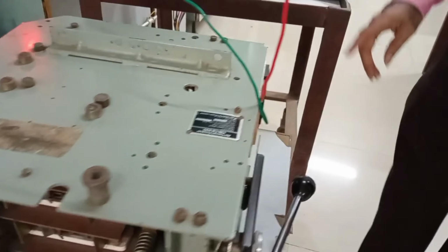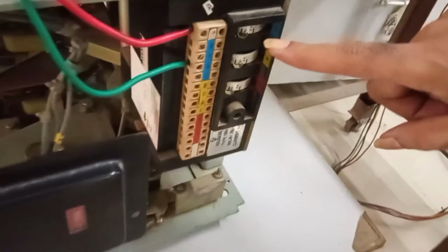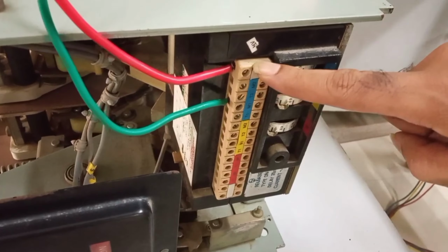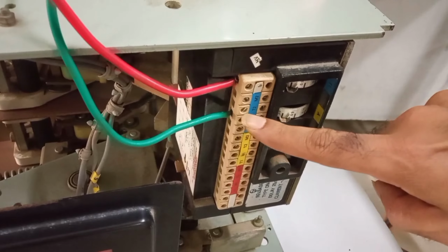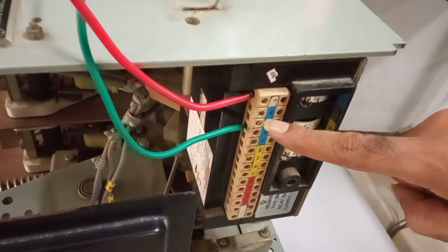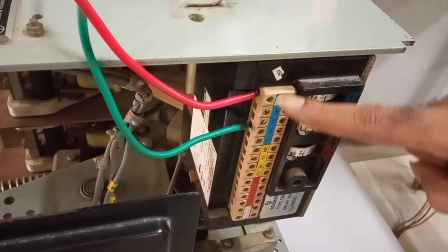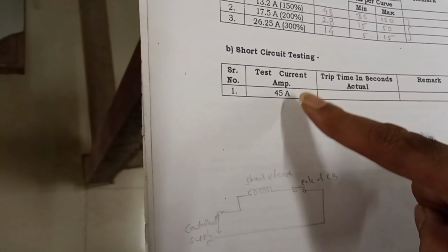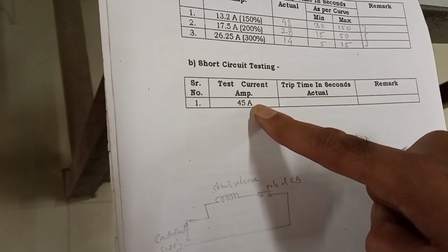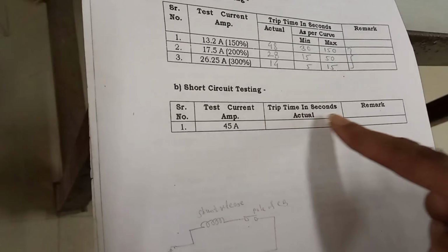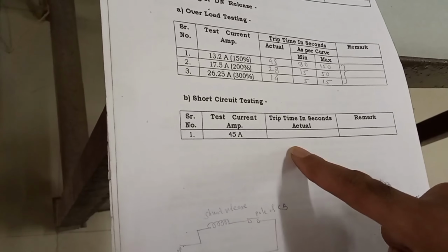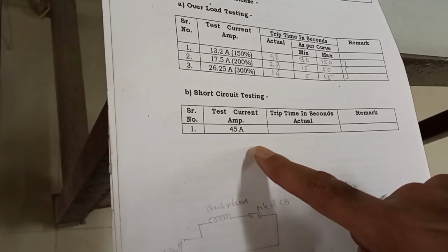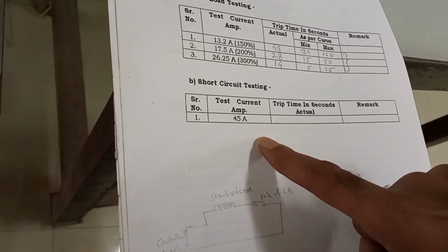Okay. Now for the connection of this short circuit test, I have connected S and M1. The red wire is connected to S and the green wire is connected to M1. So between S and M1 our magnetic pickup coil is connected, and these two red and green wires are connected to the current source. Okay. And how much current do we want to inject? We have to inject as per the instruction given by L&T in the manual. We have to pass 45 ampere of current if we choose the tap S and M1 as we have selected. If we select S and M2, then we have to inject 57 ampere of current as per the instruction of L&T.